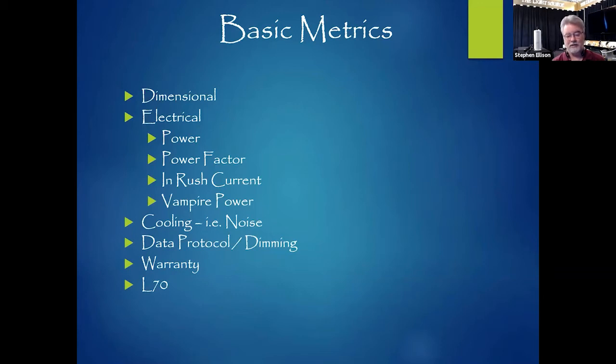And so you've got to calculate that in, that you're going from everything being easy to suddenly you're loading up the neutral a lot more. Computers, nowadays, offices didn't have computers. Now everybody's got a computer. They're using switching power supplies. So you'll find that the electrical engineers are dealing with that and they'll understand it, but they'd like to know that information. And the manufacturer should be able to give you that.